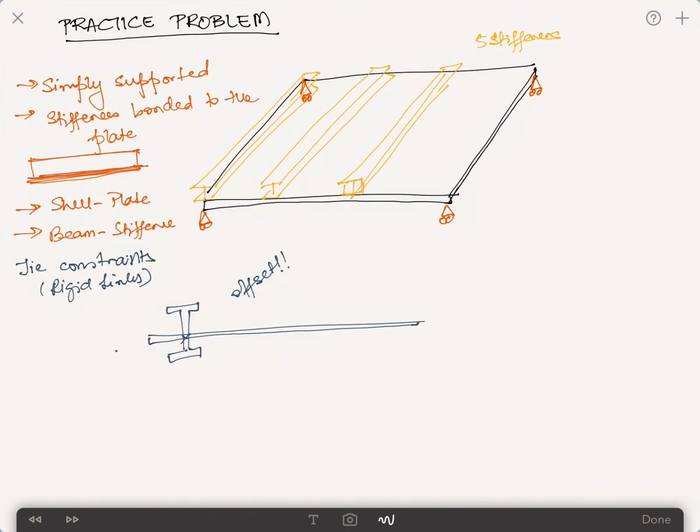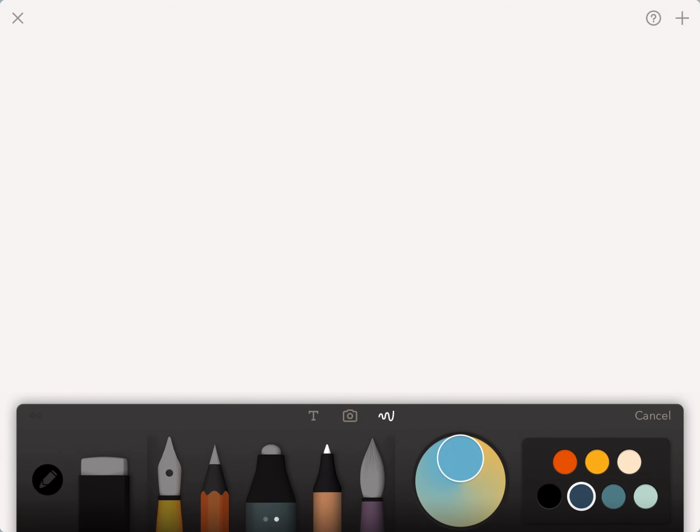And you will have a pressure load acting on it, a uniform pressure load across the entire plate, and the value has already been given in the assigned practice problem sheet. You also have all the dimensions. Dimensions are in inches. The pressure is in PSI. The properties are in KSI. Work out this problem and see if you can get yourself to understand tie constraints by means of this particular example. Now there are certain rules that you have to follow while creating these tie constraints.